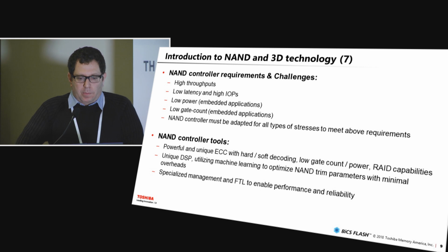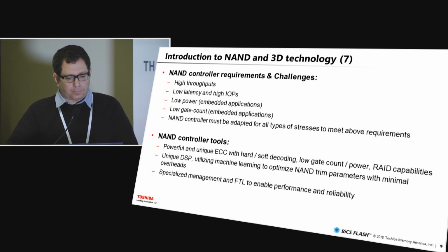So what are the requirements from the NAND? Well, you require from the NAND controller high throughputs, low latency with high IOPS. When you look at embedded applications, on top of that, you also require very low power and low gate count. The result is unique ECCs and unique design to make sure that you can still support very high performance, but with very low power and low gate count. And of course, the NAND controller must adapt to all stress types, all conditions that the NAND can lie in.